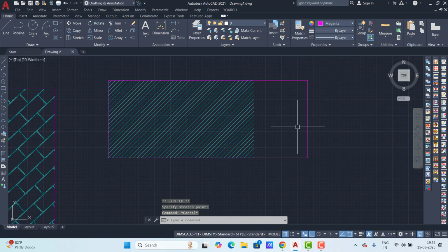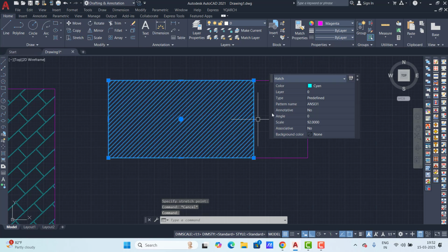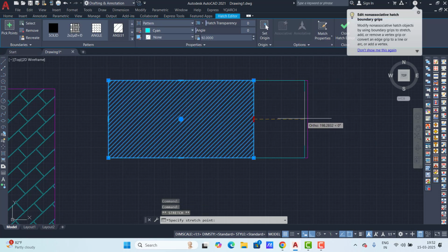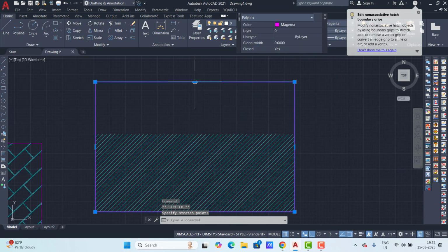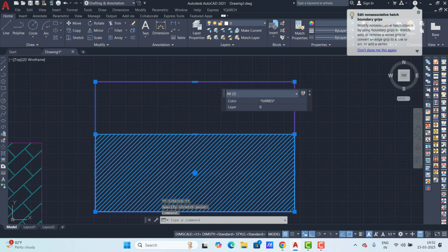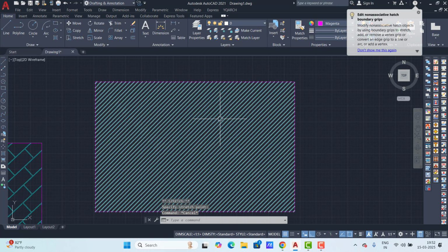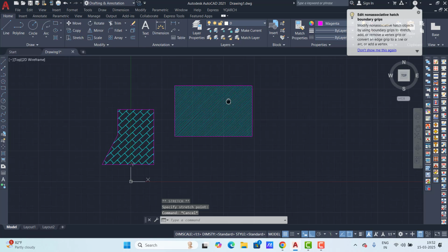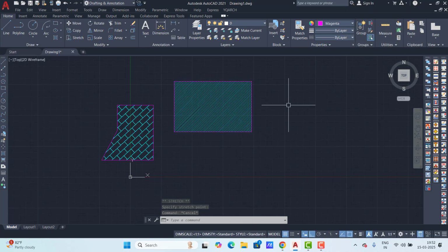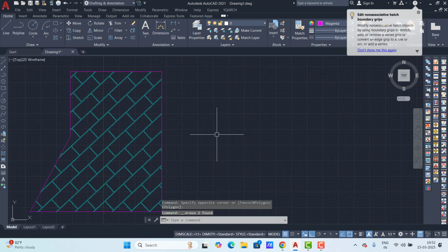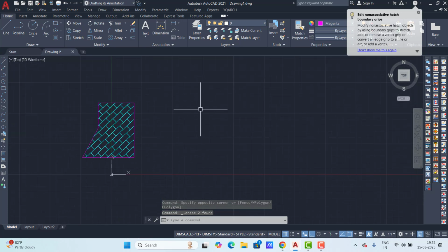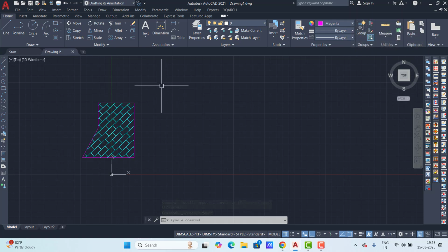So with the boundary command, we can create polyline objects or region form objects. It only creates a boundary copy, making one connected closed boundary. So here we can create the same object as polyline form or as region form. We create two copies and see the same result but different types. So the boundary command is BO, enter.